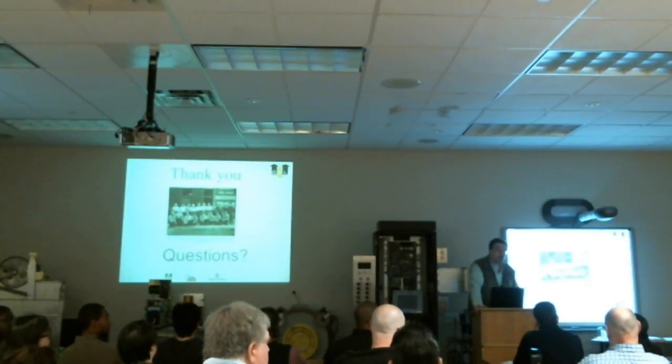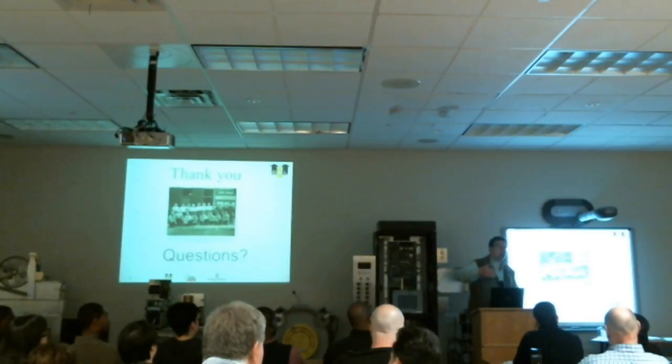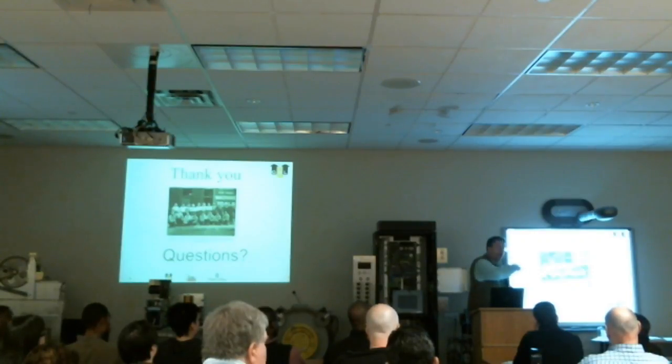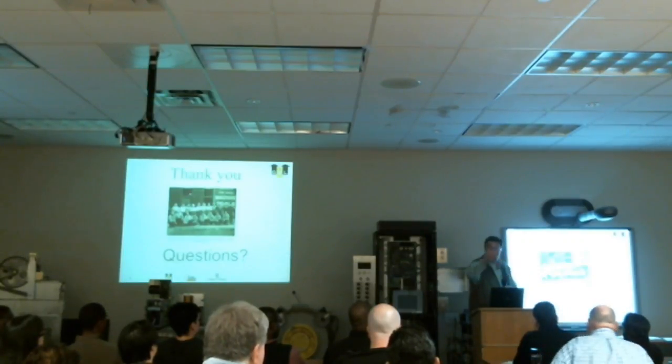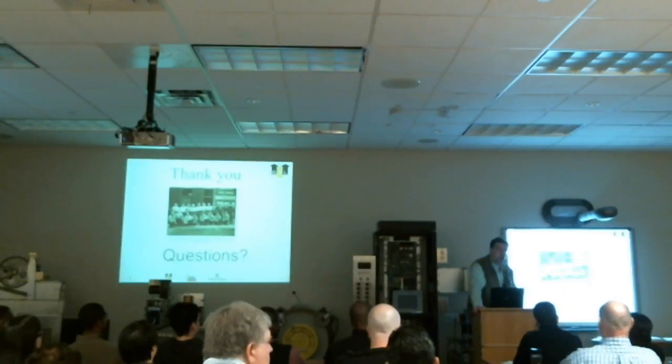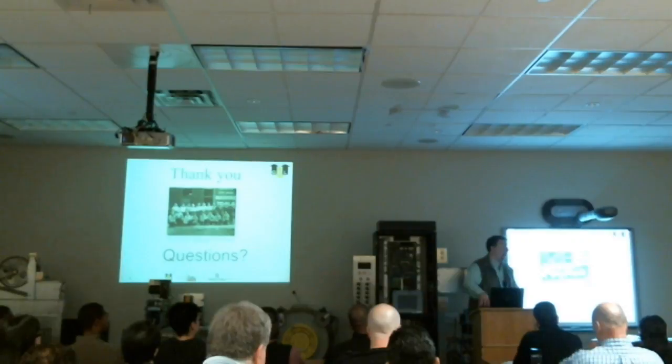So, we try to tell a lot of these contractors. Where they get caught is when they do what they call Category 1 and Category 5 testing, yearly or 5-year tests. They actually test door lock monitoring. A lot of contractors don't know they have to comply with it, and then guess what? They fail. They contact us, saying, I did this test, it did not comply, and then we provide them with the software upgrade. So we try to tell the contractor, listen, you've got to update them when you do your next Category 1 or Category 5 testing, because they test that.